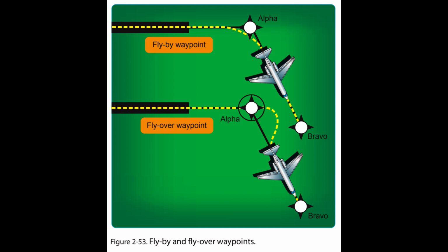User-defined waypoints. Pilots typically create user-defined waypoints for use in their own random RNAV direct navigation. They are newly established, unpublished airspace fixes that are designated geographic locations/positions that help provide positive course guidance for navigation and a means of checking progress on a flight. They may or may not be actually plotted by the pilot on en route charts, but would normally be communicated to ATC in terms of bearing and distance or latitude/longitude.